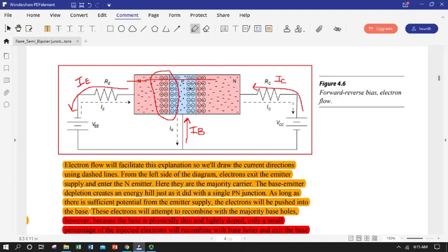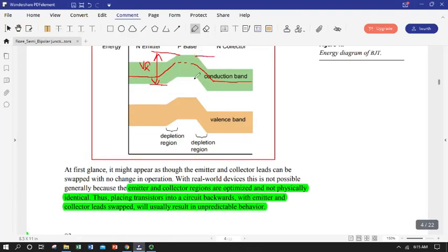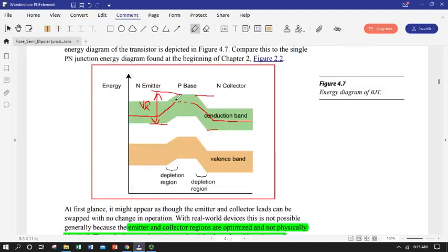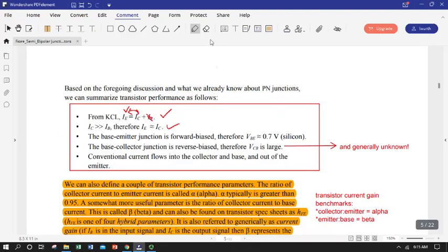It's important to remember we have no clue what this one is. The size of this really big hill, we don't know what it is. We always have to get this from inference by difference from looking at other things in the circuit. We get this from Kirchhoff's voltage law for the rest of the circuit. But we know the base to emitter junction. If it's open, if it allows current to flow, we know we have supplied the forward bias voltage. And again, that's going to be 0.7 if it's silicon, maybe 0.3 if it's germanium. Whatever it is, it's going to be that known characteristic of a semiconductor. And for this class, that's pretty much always going to be 0.7. So there's something we know.